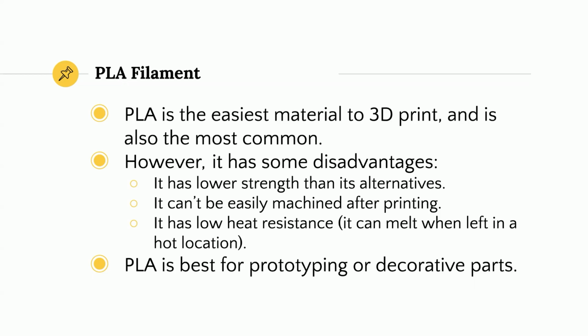I would put a caveat on this though. If your 3D printed part does not need to be very strong and you just have a bunch of PLA sitting around, you can use PLA. Like if it's a moving part but it doesn't have to be strong, you can use PLA. It's not that bad. Some of these next alternatives might be better, but they have some downsides. Just remember that PLA is always an option. But if you're talking about what it's best for, prototyping and decorative parts.